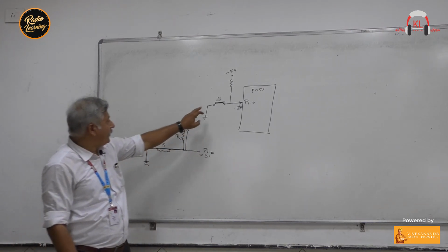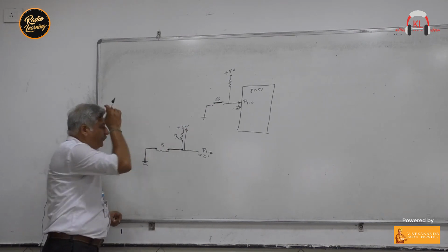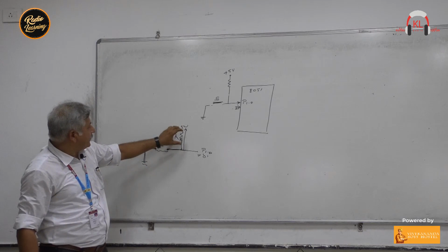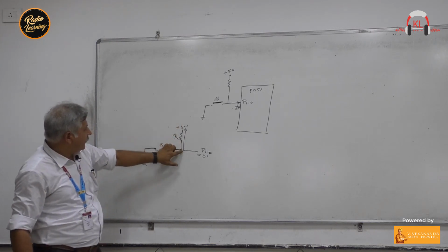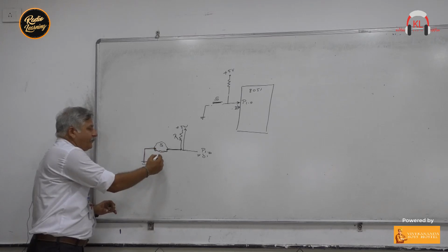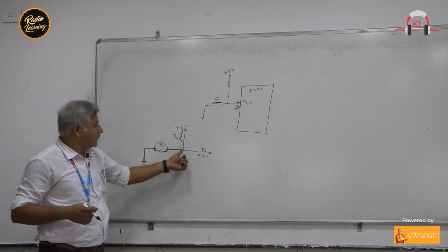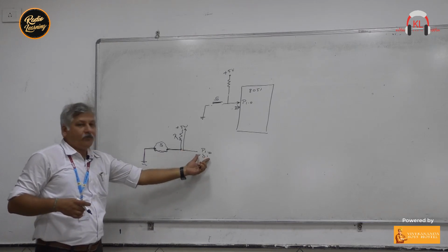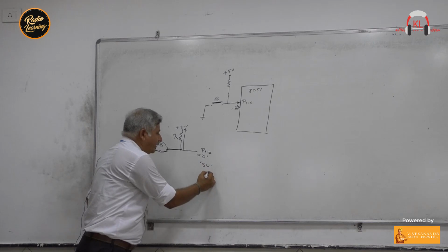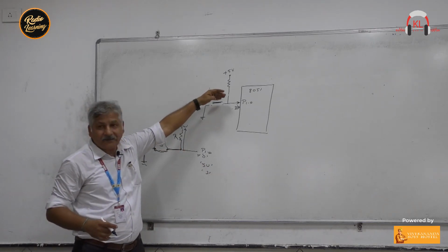And when we release this switch, this is an open circuit path. This point is connected to VCC through this resistance, and to ground through this open circuit. Open circuit means very high resistance, in the range of megaohm. So if we read the voltage here, we find plus 5 volt, that is binary 1, when we have not pressed the switch.